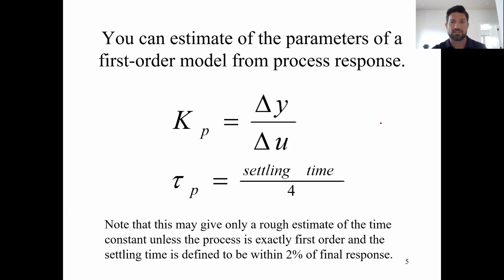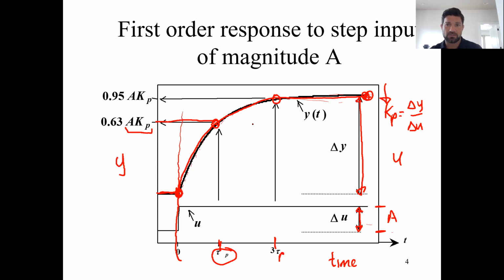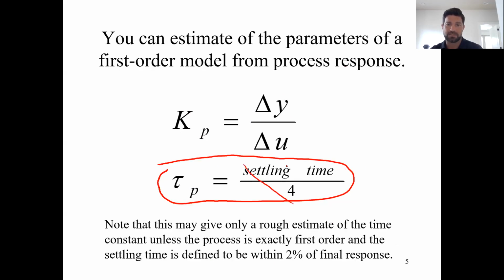Here's some information that we talked about a little bit. The book talks about this in terms of settling time, which is about when it gets to the new steady state value, about 100%, like 99 point something. I don't like this at all, because once you have noise in there, it's hard to distinguish the noise from where you are. So for a first order process, use this behavior, use this plot. Don't use settling time. It isn't necessarily very useful.